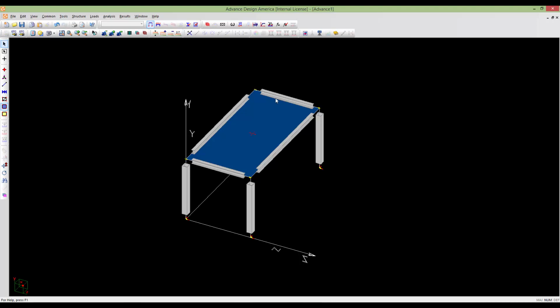To apply the loads to the structure, you need to go to the loading mode or load case mode. You need to activate this mode. As you see here, we have different modes, and we will discuss all modes here. The first one is the structural mode that we build our model on. If you want to modify the model, delete or add some members to the model, you need to always be on the structure mode. And if you want to work with loads, add loads, remove loads, or check loads, you need to be in this mode, load case mode. Okay, so I'm going to click this, and as you see, we have the already defined load cases, the dead, live, snow and wind.